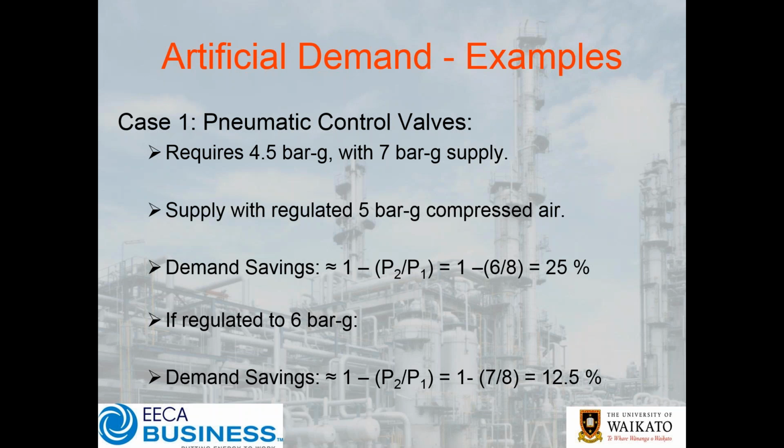So I want you to think about this for a minute. If you've got valve banks, and they're actuating, by simply regulating the air pressure to that valve bank, you can reduce your air use by 25%. 25%. That's a substantial penalty that you pay through simply some lazy engineering or system specifications.